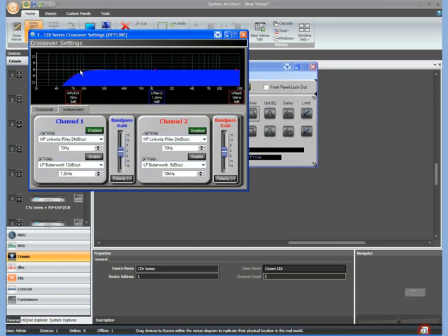In the transformers that we use in the JBL control series speakers, these are very high quality transformers, so we can in fact lower this frequency and get more bass out of them than we could with most other speakers. In this case, I'm going to set up a simple high-pass, low-pass crossover. I have connected my subwoofer to channel 1 and my satellite speaker to channel 2.